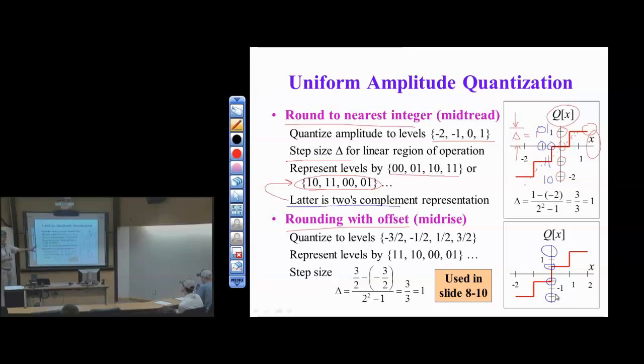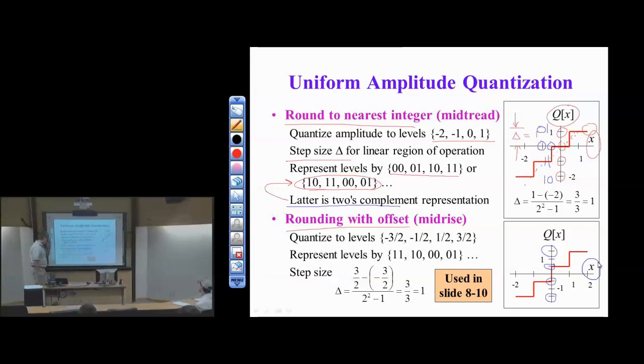So here it's a 2-bit quantizer, 4 levels. And again, I'm just changing where the thresholds are happening. So if X is between 0 and 1 on the input, then I'm going to end up at a half volt. And you can kind of eyeball this, saying my quantization error is, worst case, when X is 0 or something very, very close to 0, I get a half.